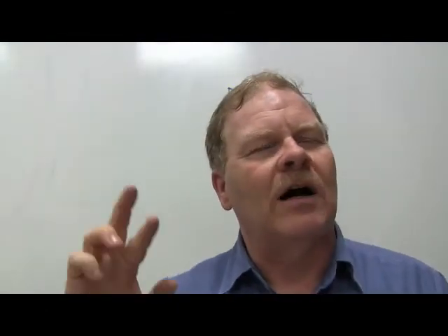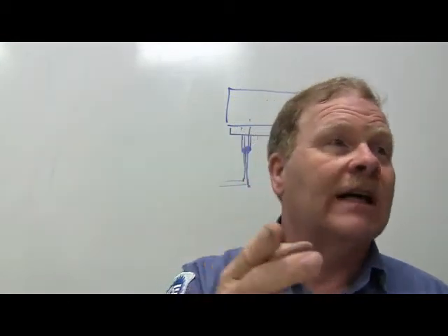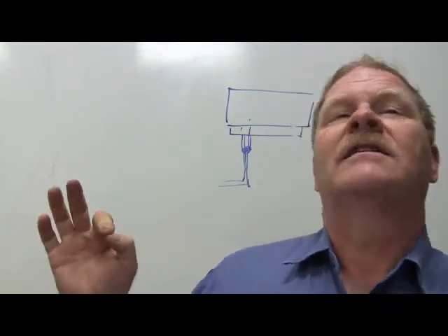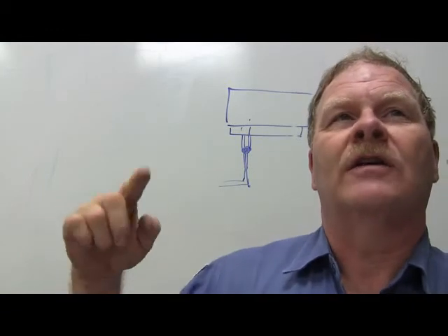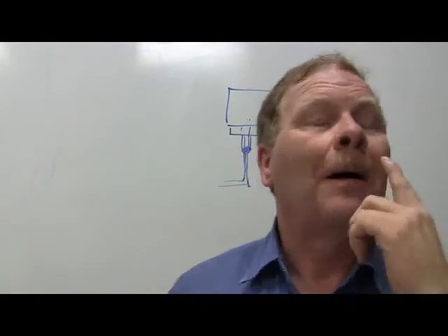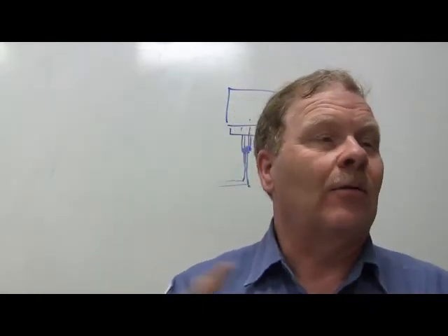So anytime you see wires that are twisted around one another, particularly network wires, if you have to fix a circuit, you're going to have the same number of twists per foot as they had before. You don't just fix them and let the wires stay apart.